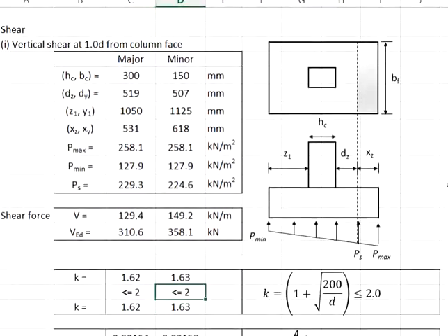In terms of the shear resistance, also because of the Z1 and the Y1 distance, the minor axis will engage more stresses outside of the column. This indicates that when you have a shorter effective depth, a larger region of stress outside of the shear plane shall be engaged. As a result, you will have a higher total shear force in the minor axis.